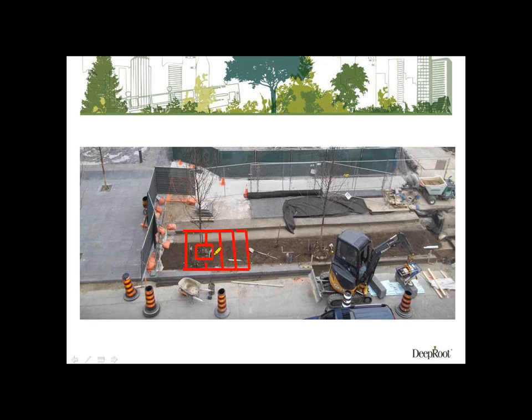So looking down in plan view somewhat, this gives you an idea. Here's your concrete curb piece. Here's your back piece. These are how the panels will be laid in, and then eventually the same paving pattern will be brought over the top of these precast panels to make everything come together.